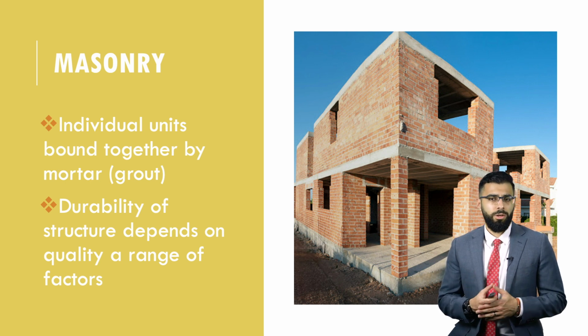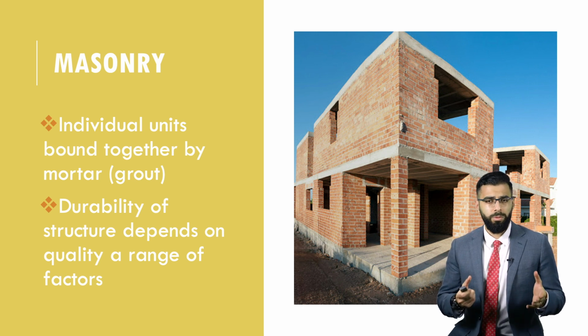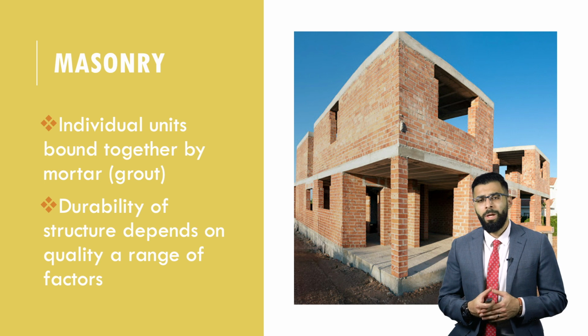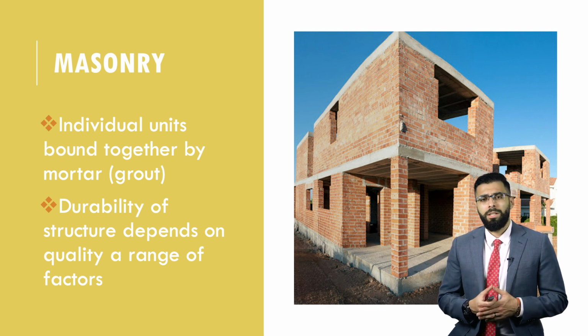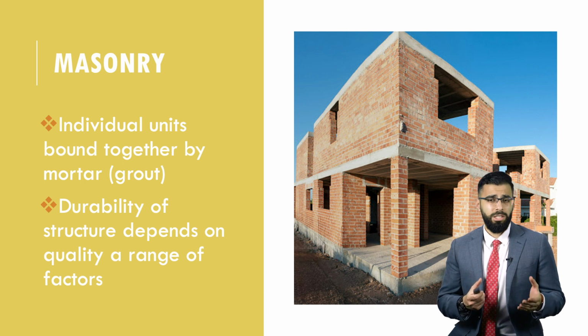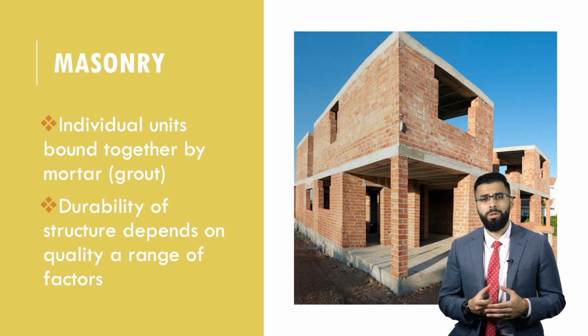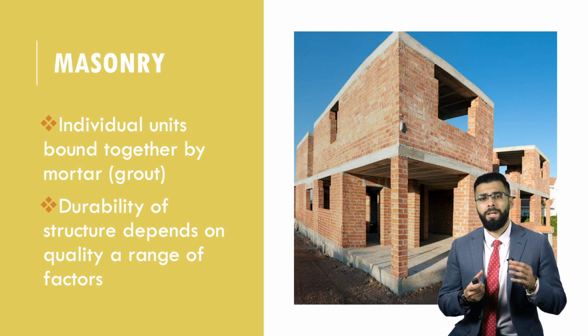You can also find structures such as columns that are built from masonry. In terms of its durability, it's very durable. Depends on the quality of the masonry units that you use. It also depends on the mortar that bounds together the units, and also on the laying pattern.